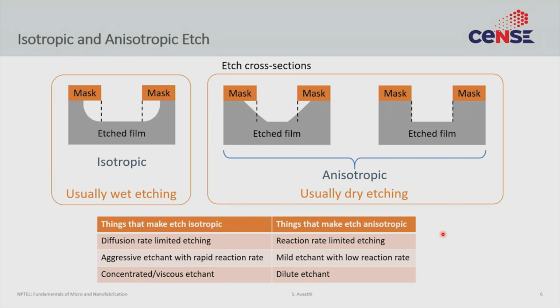So I urge you to remember the lectures on diffusion, where we had two cases, where the deposition precursor was coming in, diffusing through a boundary layer, getting to the surface and doing a reaction. We talked about how these two fluxes, the diffusion flux and the reactant flux, have to be in balance. That led to two different regimes where the deposition reaction could either be diffusion limited, or mass transport limited, or surface reaction limited.